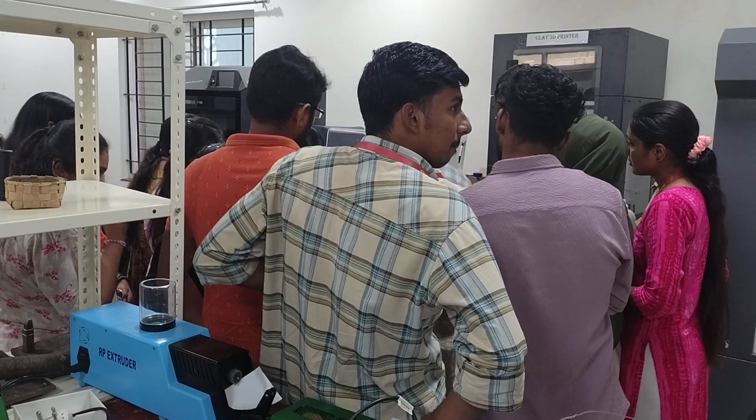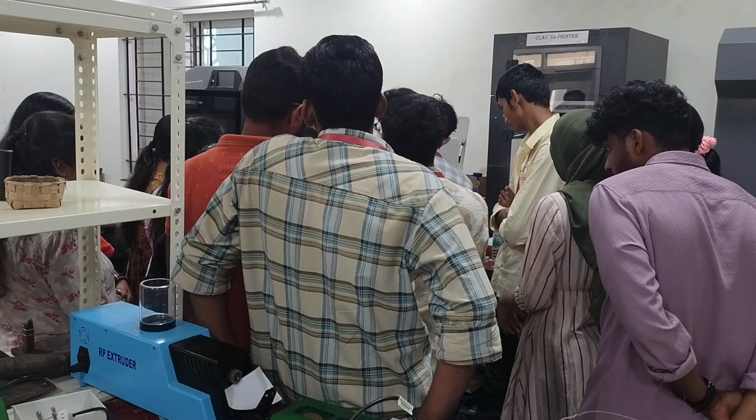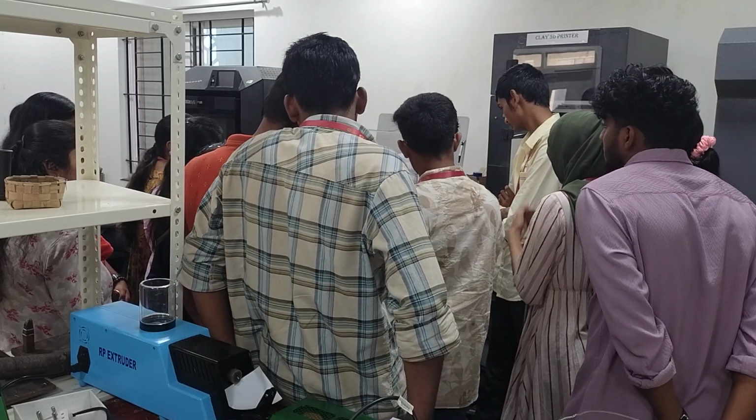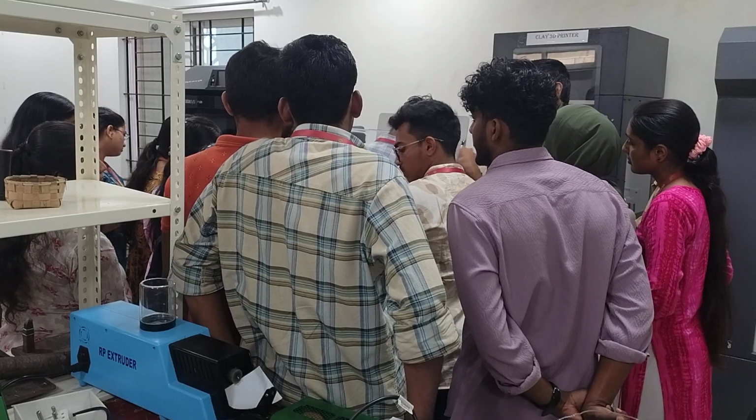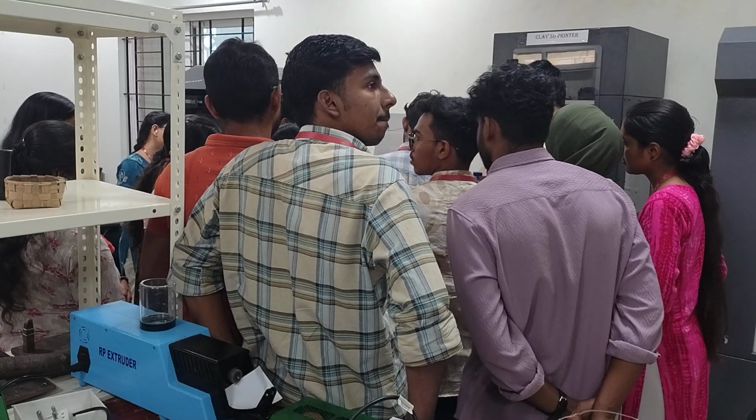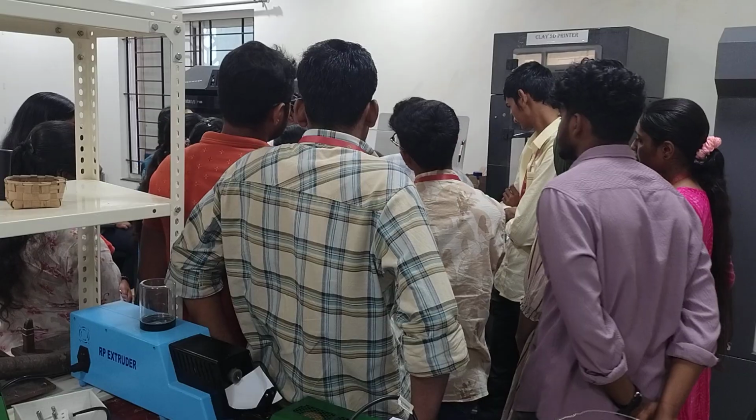Remove the filament from the plastic bottle tube. From the plastic bottle tube, I've already removed it. From the outlet of the extruder, there also I've removed it. And attach the feed tube to the inlet of the extruder. This feed tube is there, I'll attach it to the inlet of the extruder.